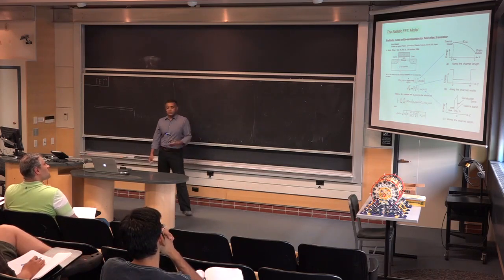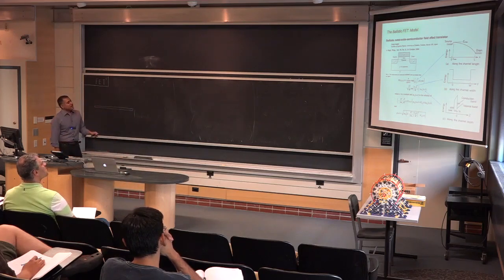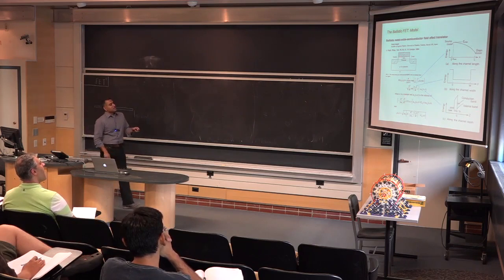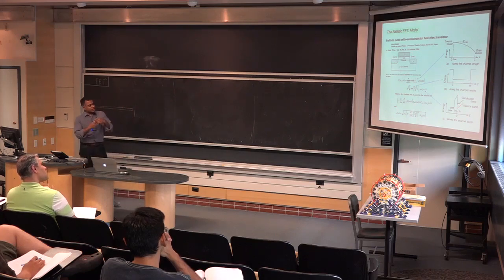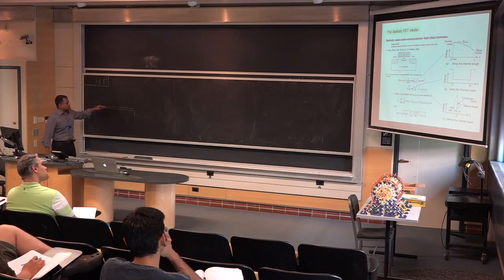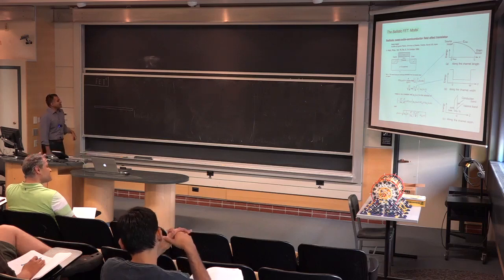But I want to assure you there's really no difference between what we're doing and what they do. Because it is a 3D semiconductor in which you create an inversion channel using the gate, there are a lot of other things you have to worry about, like quantization and the ground state. Once we start with a 2D semiconductor, we don't have to worry about many of these things. It becomes a little simpler.